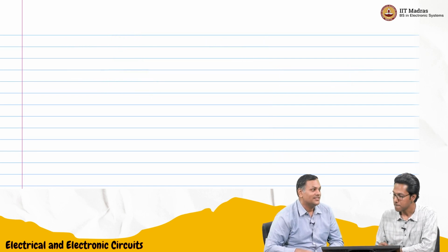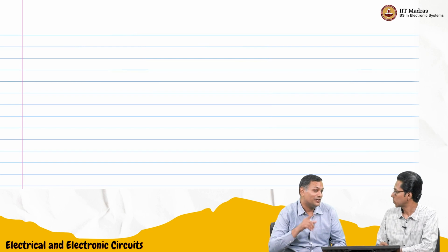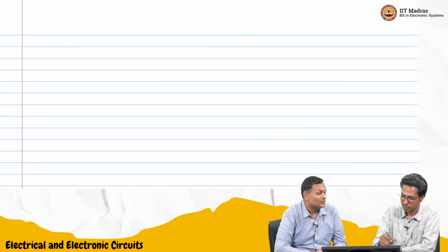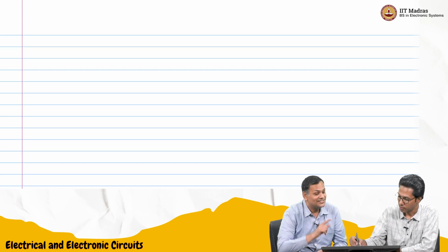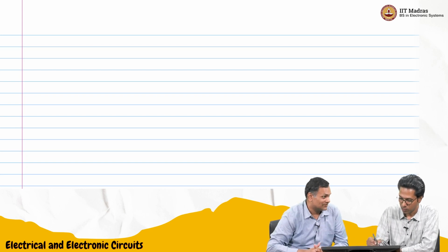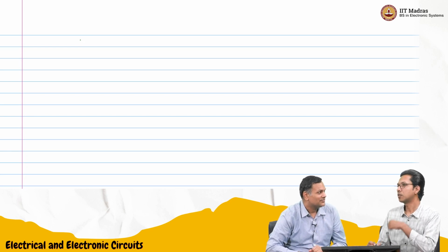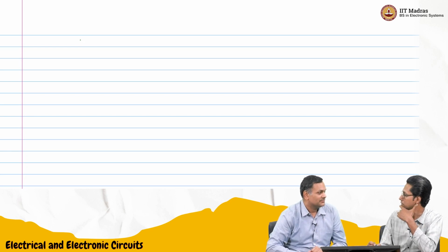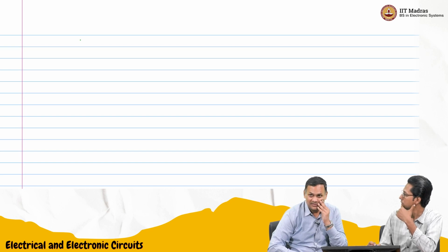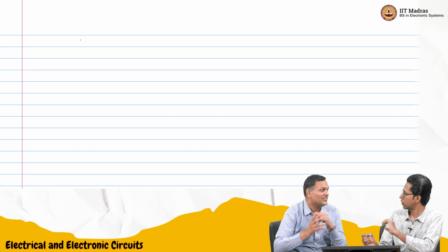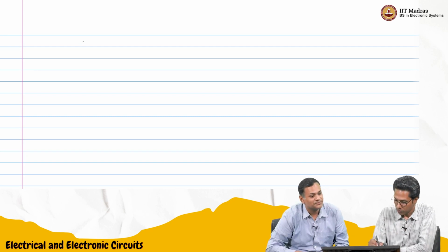We'll try one more thing. This time, I am not going to give the transfer function directly. We'll give the circuit, and then derive the transfer function and then plot. So let us take something that they have seen before. Earlier we have seen the low pass filter. Let's do one thing. We'll take the voltage across the resistor, so we will interchange the components.